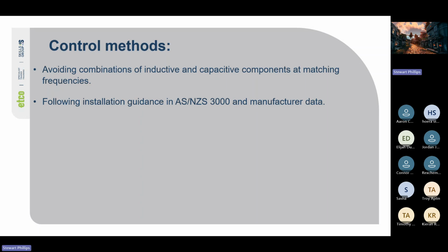Yeah, so inside of the fluoro light fittings, they have power factor correction capacitors that are normally connected across the phase neutral supply, and they have an inductor called a choke, which limits the current spikes. So they have an inductor and a capacitor in them. So there is a chance of a resonant frequency there, as well as variable frequency drives.